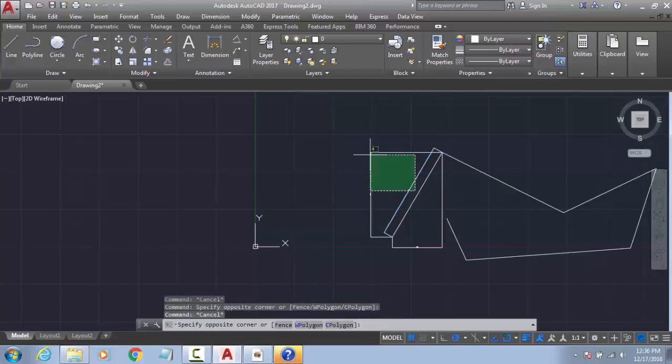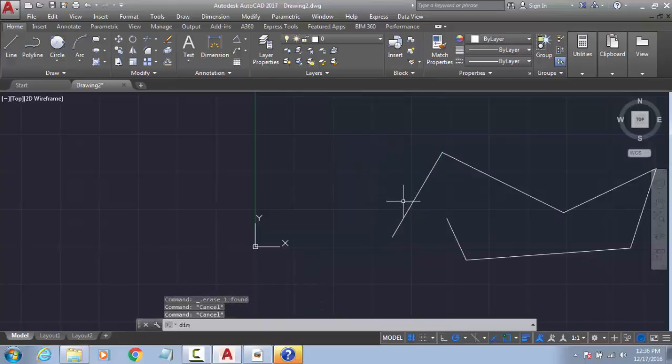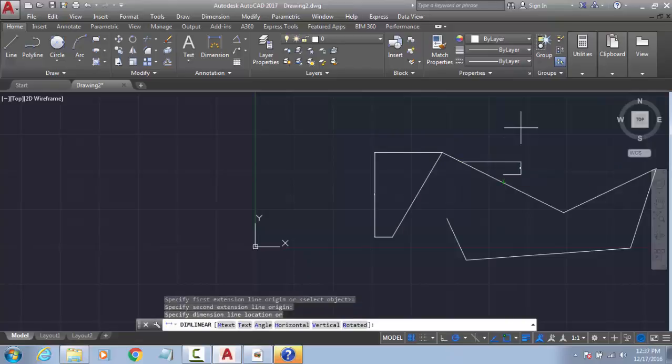Okay, you saw I am selecting just directly one line. For example, I am going to DIM LIN, enter. I am just selecting first point, second point, okay. I'm not snapping. So what I do, select object. If you press space or enter, it will now snap whole object. Now it's snapping only 2 points. So what will I do? Select and one space, it will snap whole object.